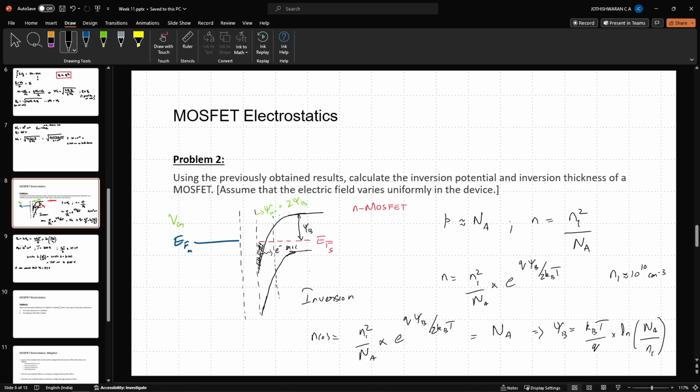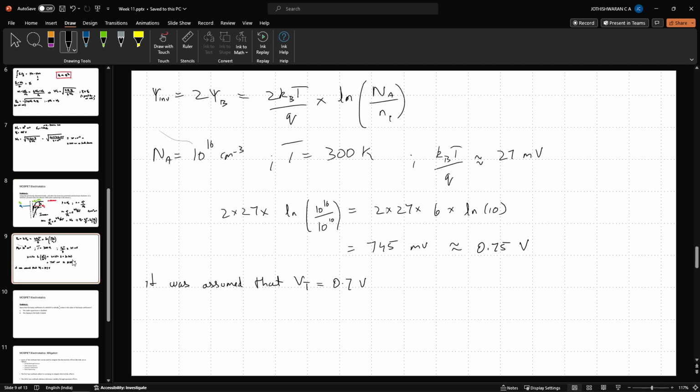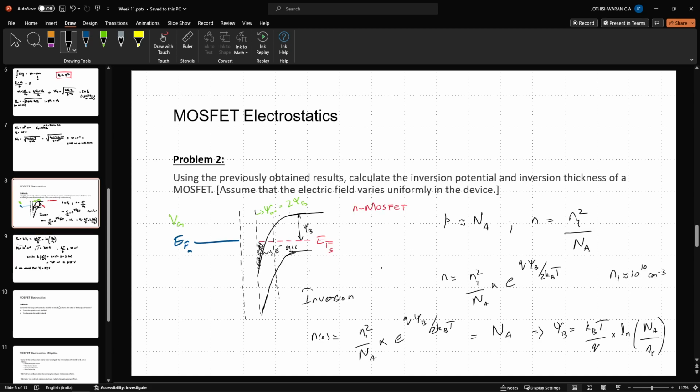To get the inversion layer thickness, we shall first try to estimate the total charge in this region, and then, assuming the uniform doping approximation, the doping concentration multiplied by the inversion thickness will give us the total charge stored here.